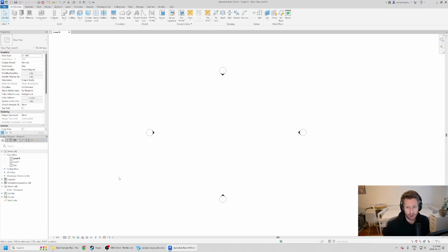So this is where all of the bits of our views, our legends, our schedules, our sheets, our families, our groups, our links, everything lives inside of the Revit model. This is important because unlike AutoCAD, where you might have different views, different sheets living separately, and then if you remember, you X-reference them in, the situation inside of Revit is that we've got everything living inside of the model at the same time.